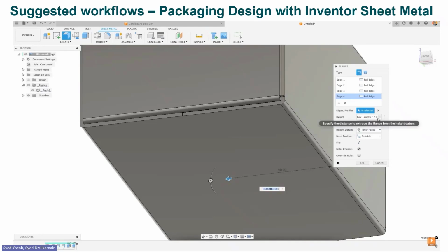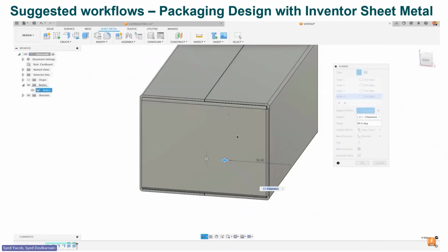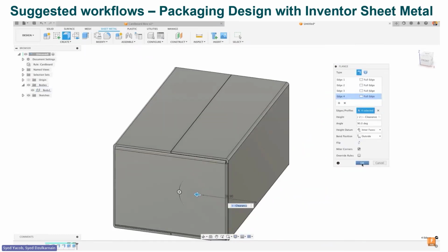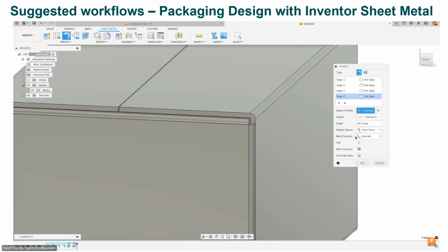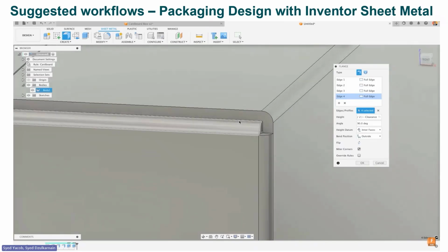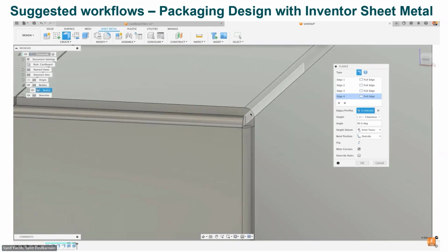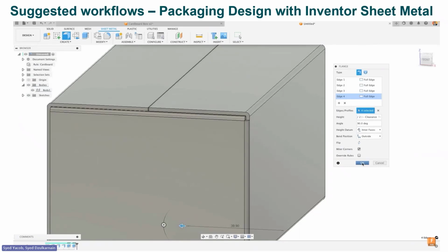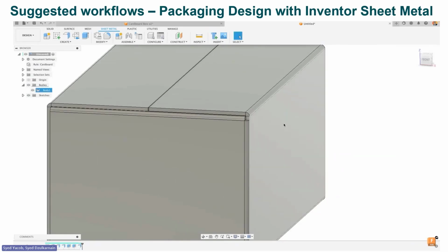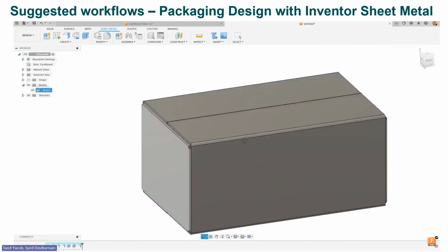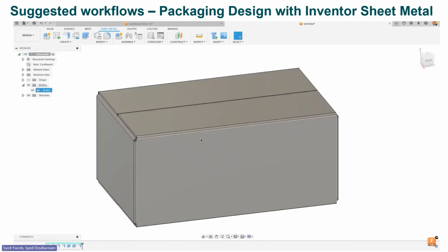You can see at the height box there, it's red, which means something is wrong. Probably the formula is not right. So I'm going to correct the formula just now. I'm using the existing parameter and adding a little bit of formula. Again, you can double check the bend positions. What's good is we can visually check if there are any clashes. Probably we should leave some tolerance, 0.01, 0.001, in case we need to. So now it looks a bit like a proper box packaging.